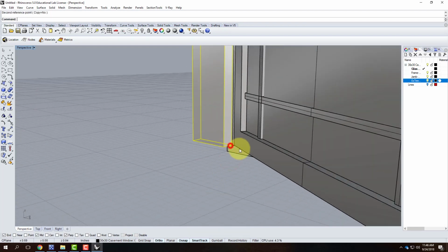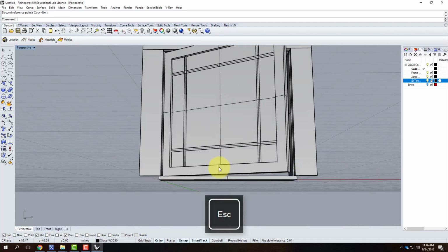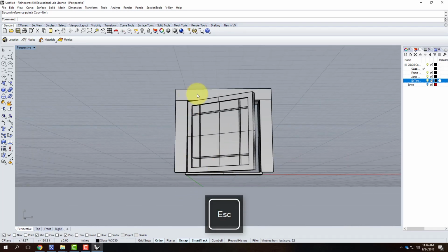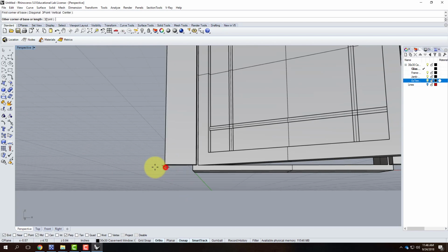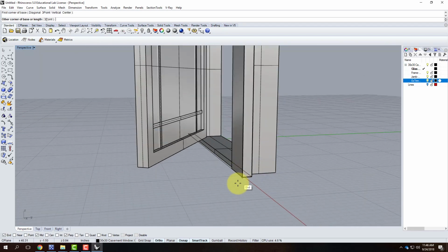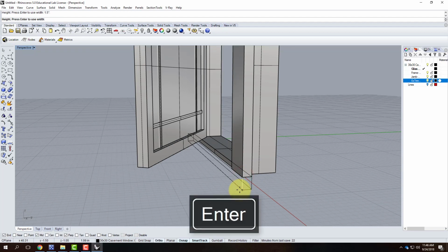And we'll shorten those up just a little bit. Now I could do another one of these down below. I could do a little sill on the edge of the window. I mean, there's all kinds of flexibility here. I could go from there to there, and we could say this is negative 1.5 inches. Let me scale 1D. Let's have this stick out, like that.